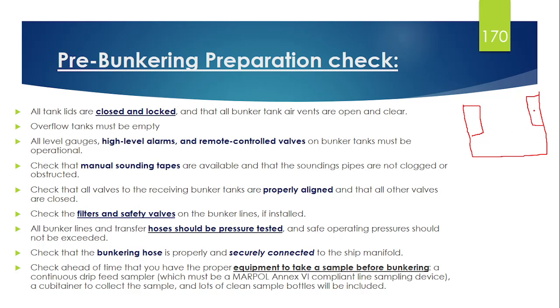This is one port and this is one starboard of a bunker tank, and suppose this is the overflow tank. First ensure that all the valves of this bunker tank are closed. When you are taking bunker in this tank and this tank, you have to make sure all the inlet and outlet valves of these tanks are closed.